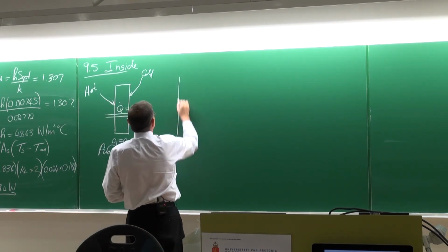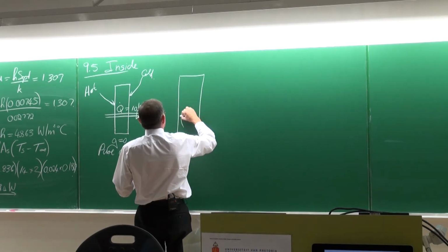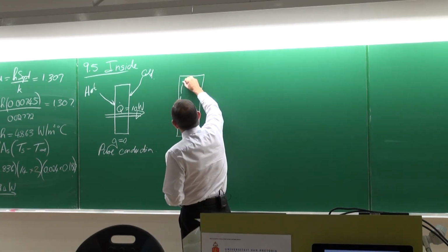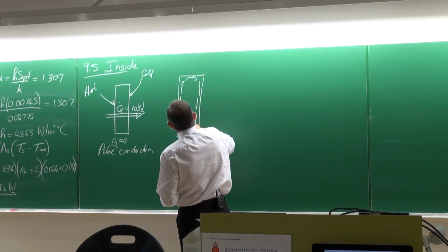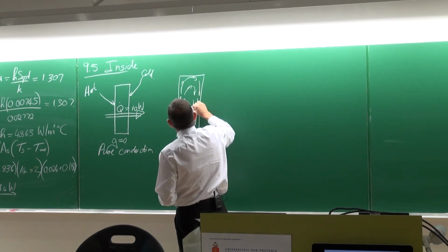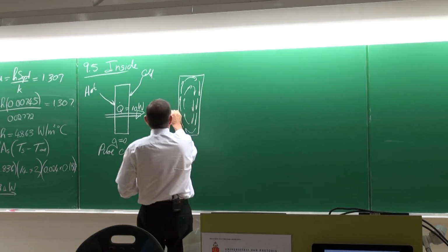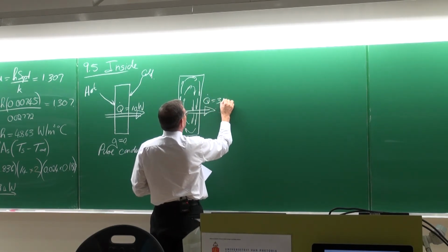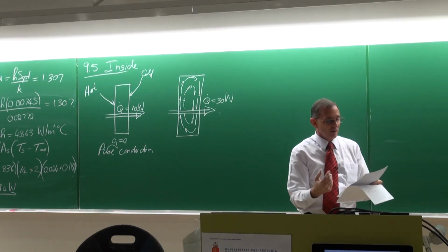However, in the real world, what is going to happen is that this part is heated, so the air next to it will rise. There it will do something like that, so it forms a recirculation area on the inside of these two glass panels. The result would be that the heat transfer rate would increase typically by a factor of 3, just because of these currents.